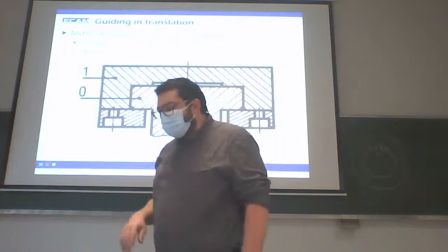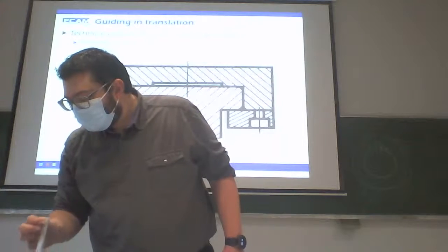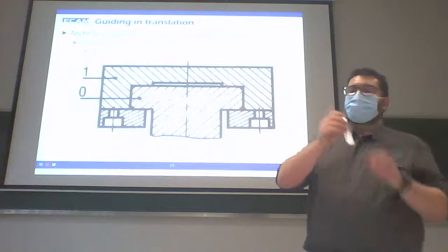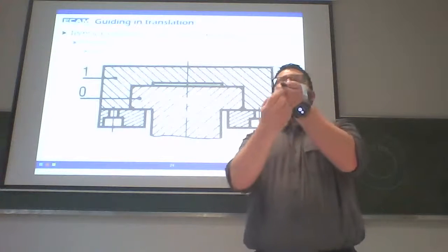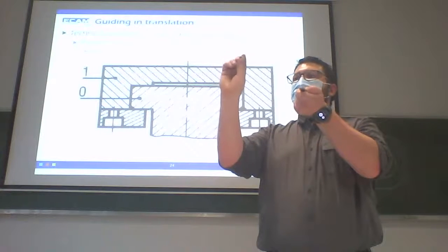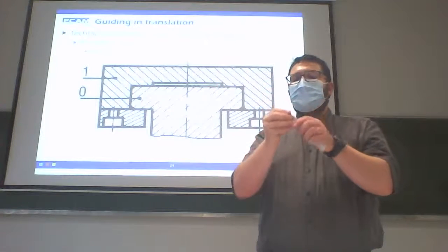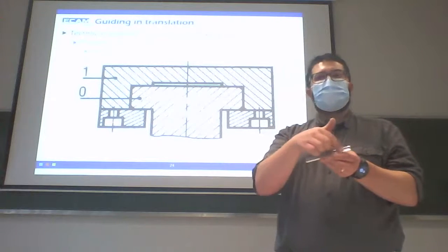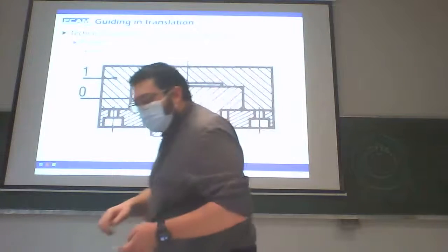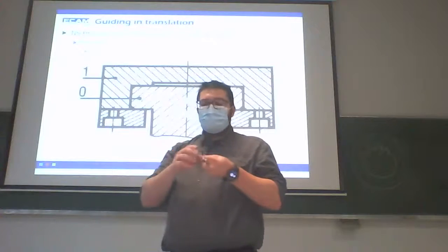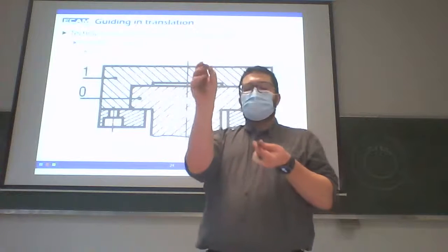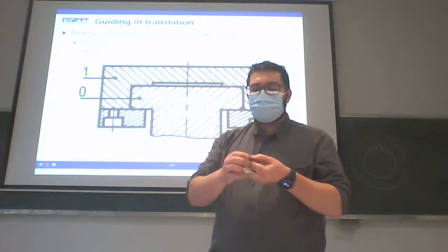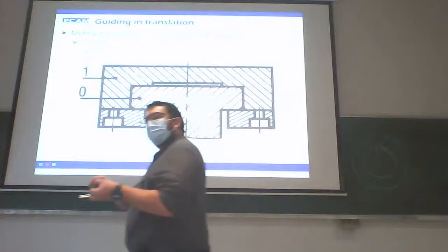For this, we can also have a passive resistance solution. You have directly inside this a T shape. The part in the middle has exactly the same shape. Here is the plastic material that reduces the friction, and you will realize a sliding joint, internal or external. It also has the T shape, and here a small part of plastic that reduces the friction between the two parts.